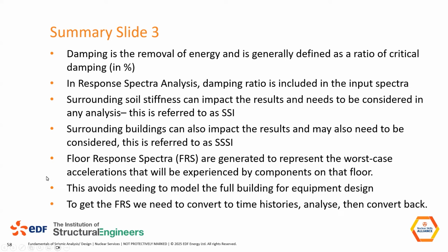And finally, for design of subcomponents, secondary structures, or equipment that sit on upper floors, we need to define a specific input associated with that floor for their design, and we do that by generating floor response spectra. To get the floor response spectra, we take an input motion, which has to be a time history. You cannot take a response spectra at the base and turn that into a response spectra at a floor. You need to take the response spectra at the base, convert it into a set of time histories, run a time history analysis, extract time histories at the floor, and then convert them to response spectra. It's one of the areas where we do need to do a time history analysis.